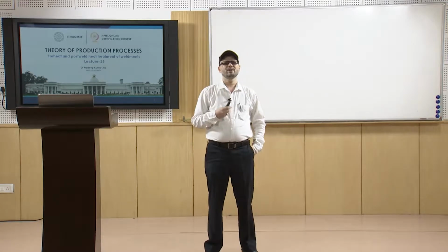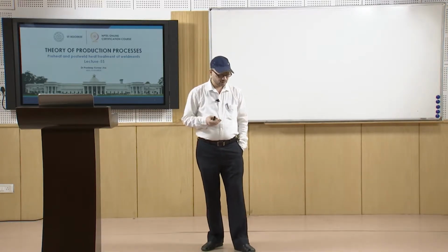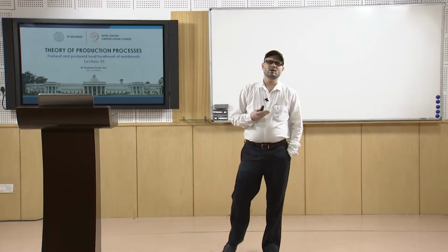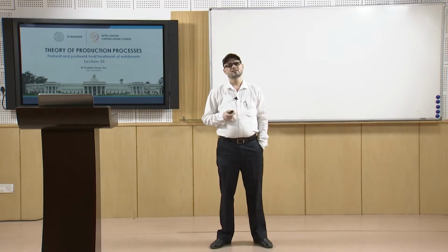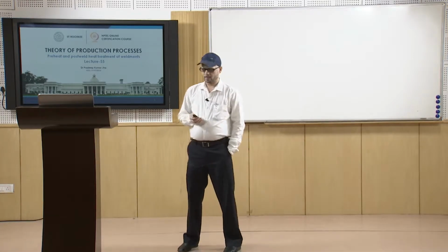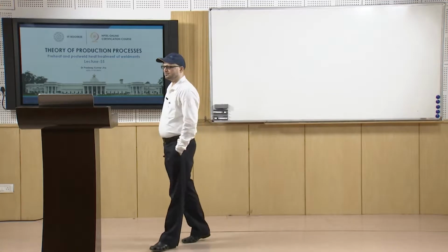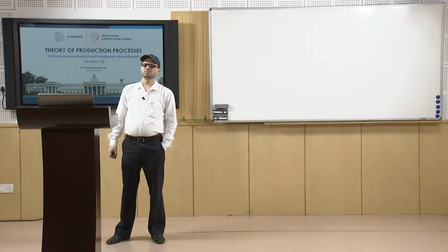One of the very important processes employed in most cases to avoid this distortion or to relieve the weldment of residual stresses is preheat and post-weld heat treatment of weldments. They play an important role.